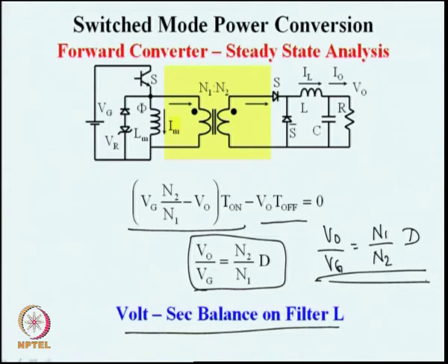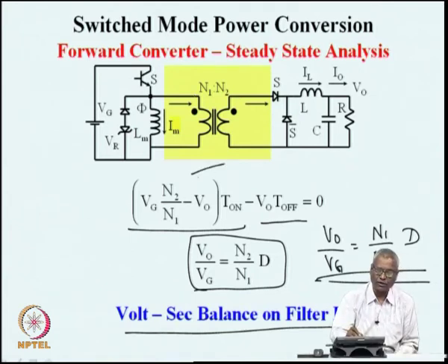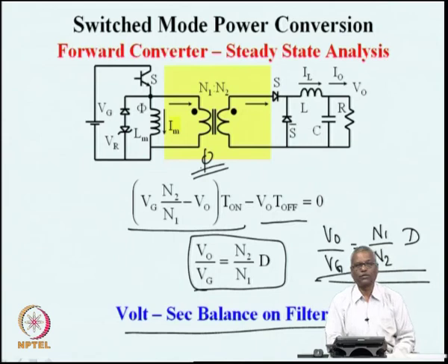This is as before, nothing new in this, but because the transformer has flux build up, we need mechanisms not to build up the flux. We went to find out the process of magnetization of a transformer and then modified the circuit so that no core flux saturation build up is taking place.